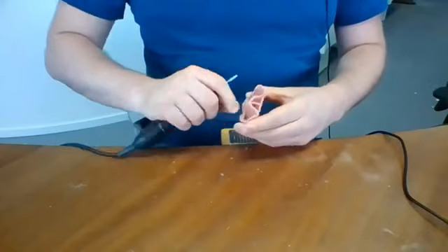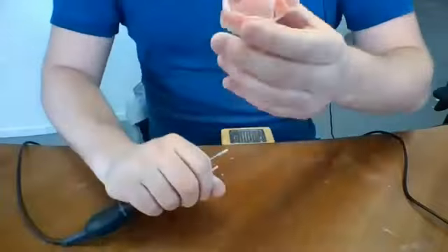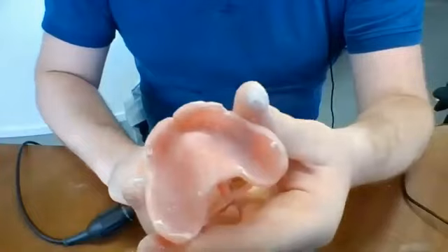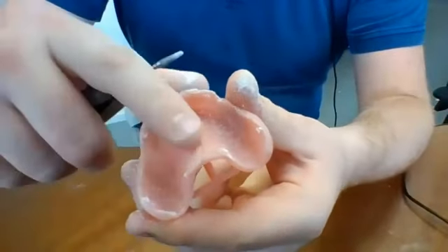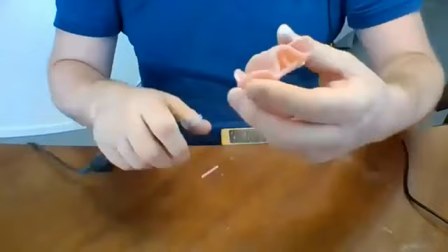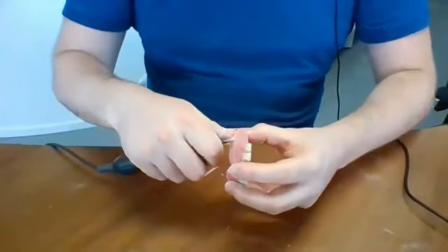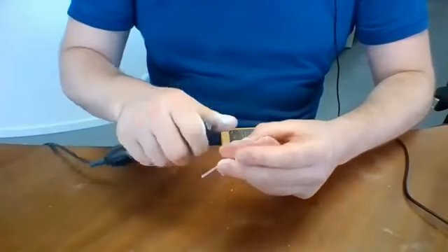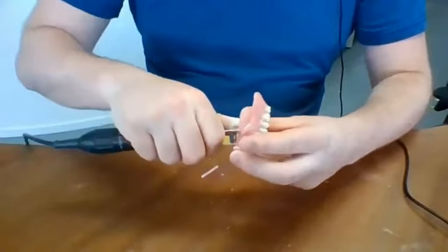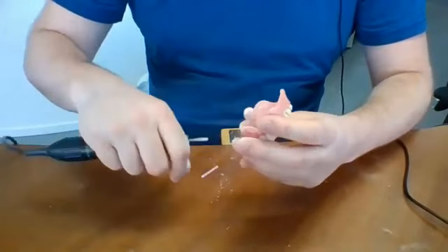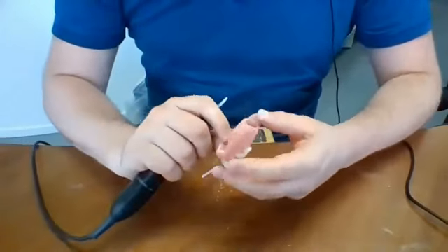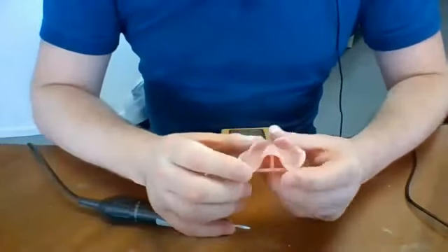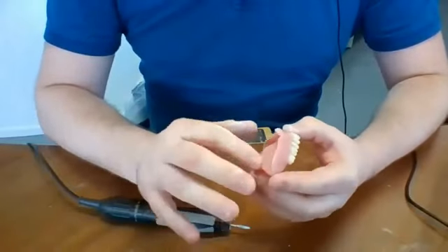Now, if you remove the bars, you will still see a little bit of the scarring of that part, which is then also very easy to remove with that tool. Just remove it, feel with your finger that it's gone. You don't want to grind away too much, of course, but it's a very easy procedure to get rid of this. After that, there is actually not a lot of work on these dentures to get rid of, for example, the rest of the supports. They just break right off. There is very minimal support scarring or material left.